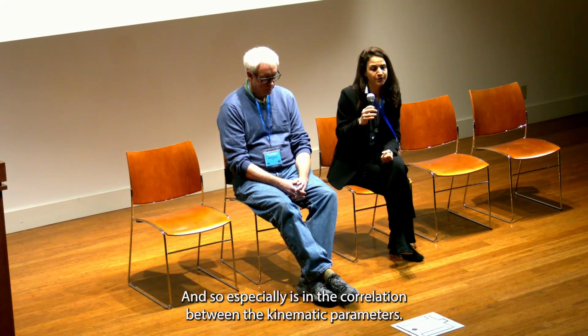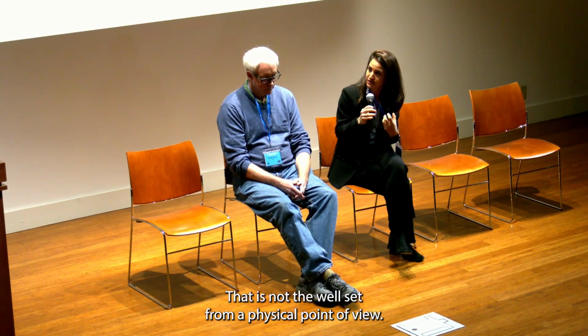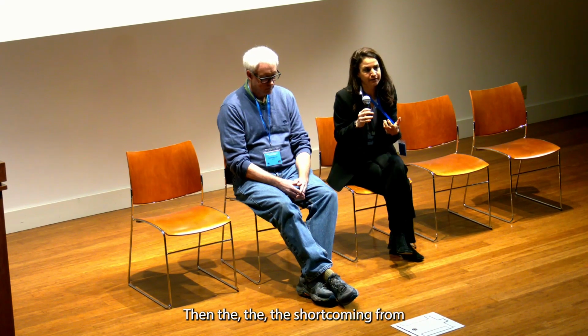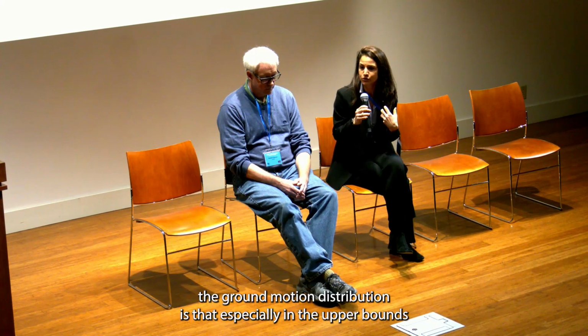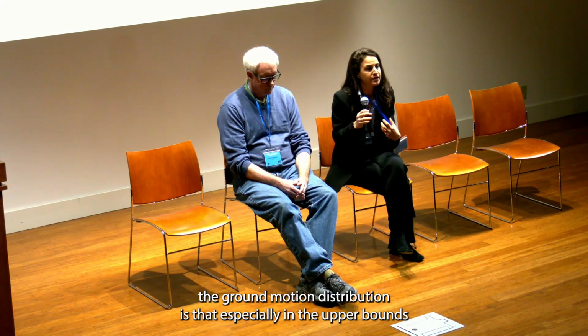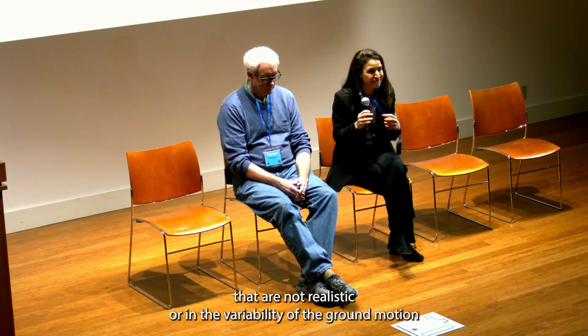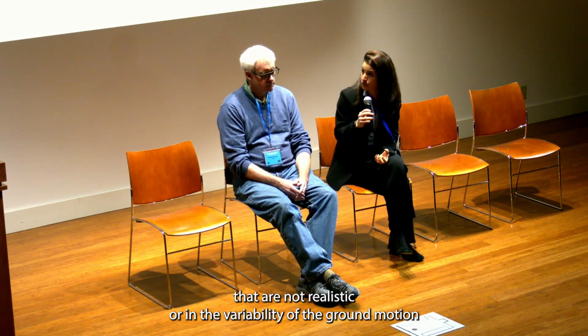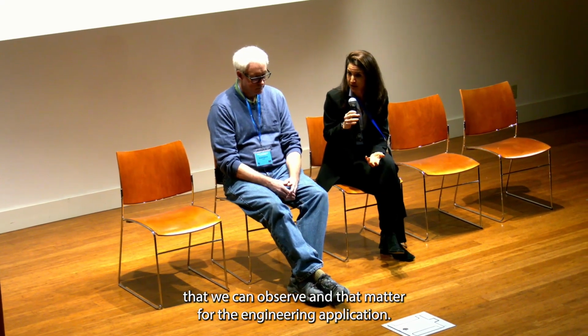So especially if the correlation between the kinematic parameters is not well set from a physical point of view, the shortcoming in the ground motion distribution is that the upper bounds are not realistic, or the variability of the ground motion that we can observe and that matters for the engineering application.